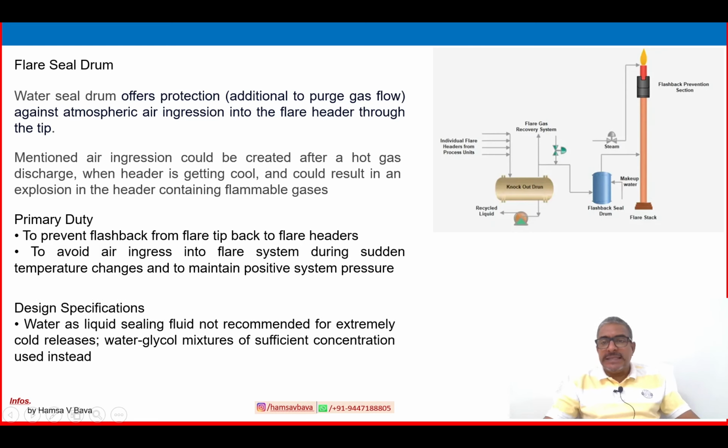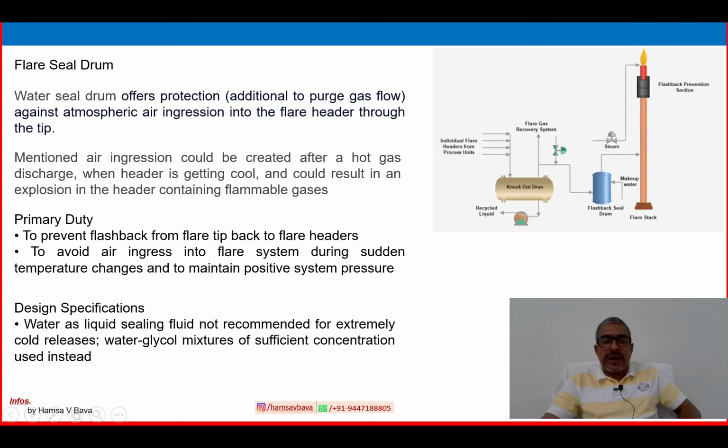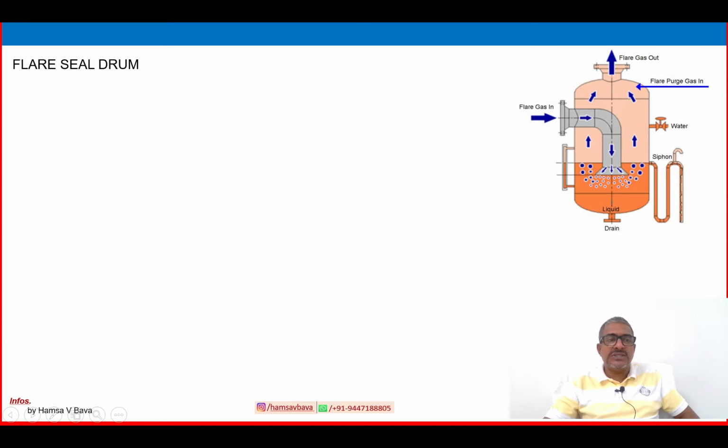Design specification. Water as the liquid sealing fluid is not recommended for extremely cold releases. Water glycol mixtures of sufficient concentration are used instead. So water can be used in summertime, but a water glycol mixture prevents freezing issues. We are using water glycol mixtures in the seal drum.